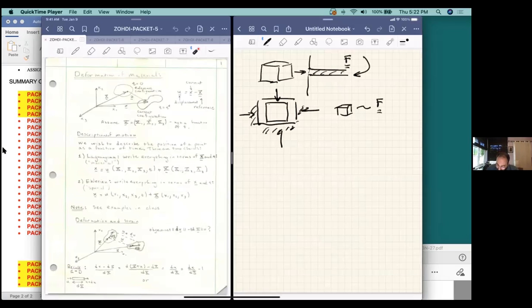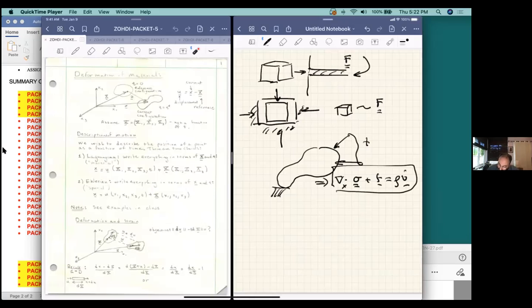But ultimately, if we want to really do a deep dive and an analysis of any kind of object that is undergoing some kind of loading on the boundary, some type of deformation and so forth, you would have to really solve the divergence of sigma plus f equals rho v dot. And if that's the case, this requires, unfortunately, FEM for almost any kind of case with a complicated geometry. So if you have, however, sometimes geometries that are relatively regular, perhaps they're some kind of an analysis of a box or some kind of an ingot, finite difference time domain methods certainly suffice and are actually faster.